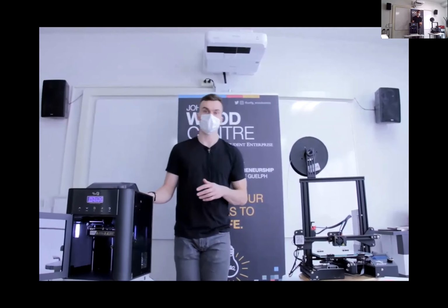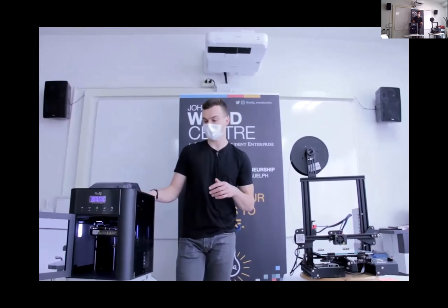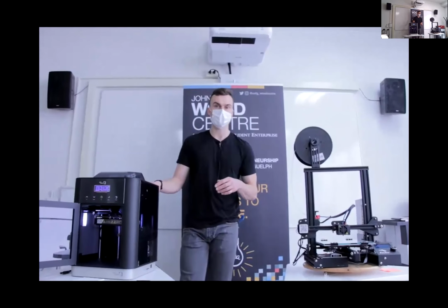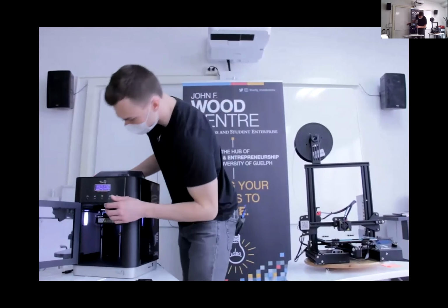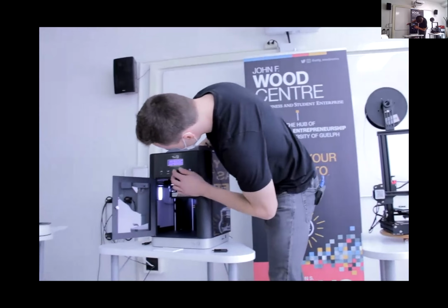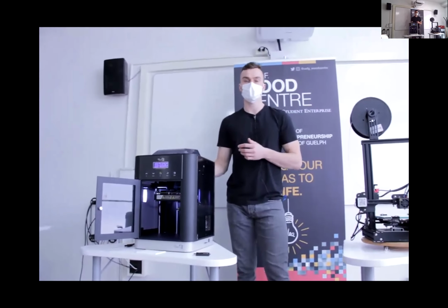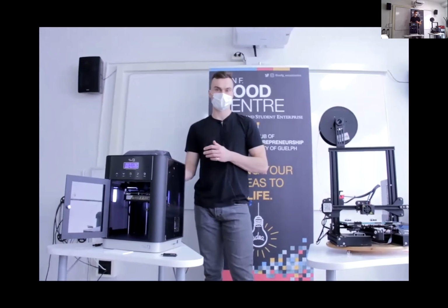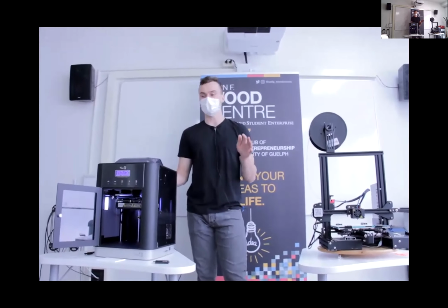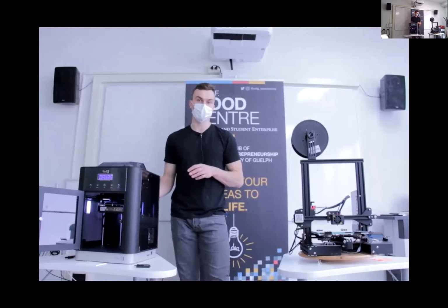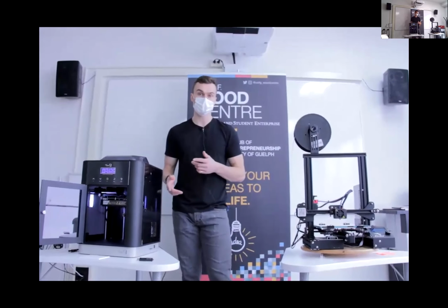There was a question about changing filaments halfway through. Technically, you can do that. You can pause the print. But I wouldn't recommend doing that, because your hot end might cool down and heat up in the middle of the print. It increases the chances for your nozzle getting jammed.